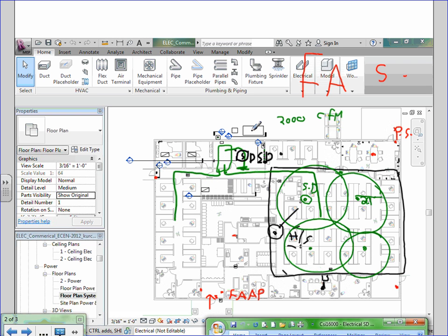If we were required to put them in the supply air duct of this particular building, Simplex, Silent Knight, whoever system you have, they recommend that you put the duct smoke detector 6 duct widths away from the unit.